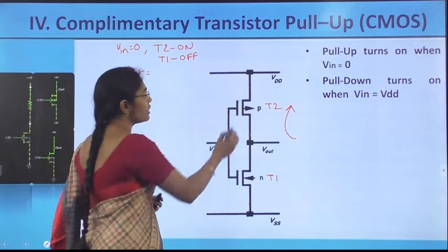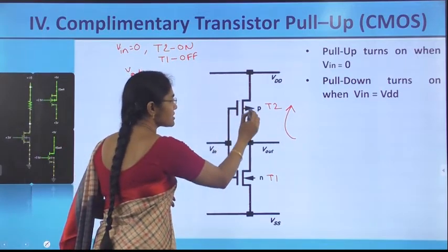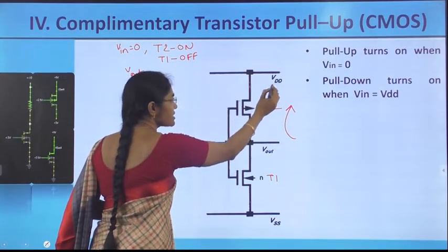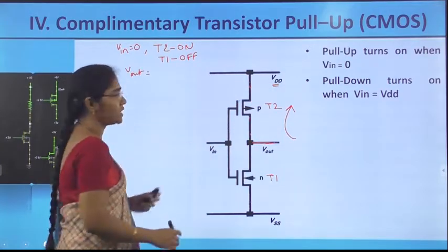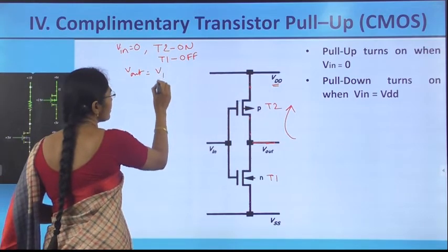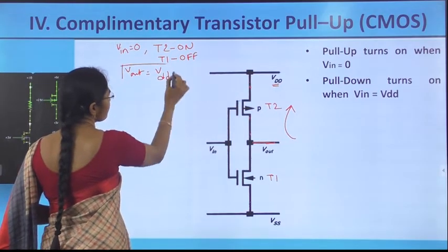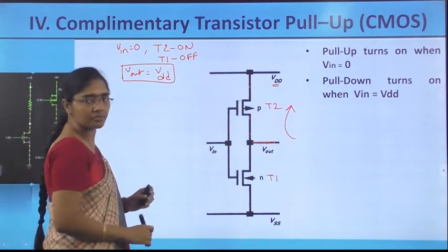And we know already, this is a PMOS pass transistor. At one end, it is connected to VDD. So, this PMOS pass transistor passes full VDD. Therefore, there is no loss, and full VDD is the output.